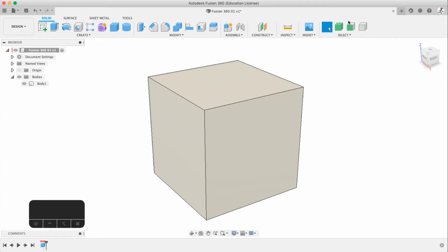The green is what you select. When you have nothing here, you can select all of them, any of them. So I can select the faces and the edges and the corners, anything you want, but you cannot select the whole body unless you click the actual, drop this down, the body, or later on the component list, and it will select the body.